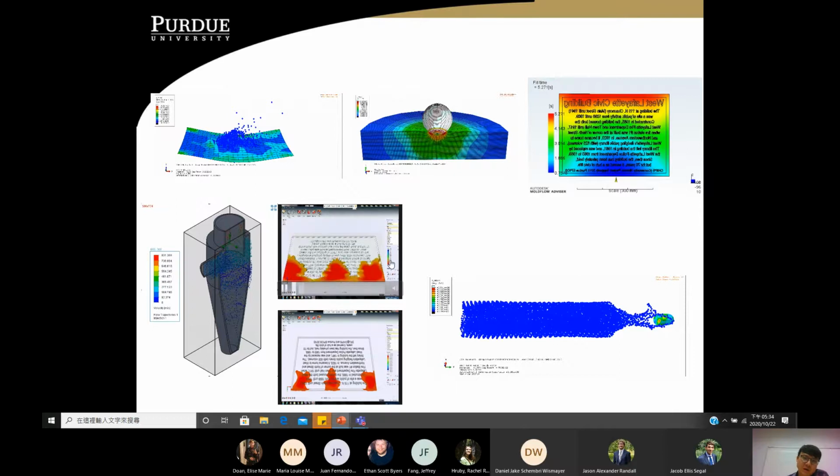You can see the aluminum filling the cavity and how it flows, so you can predict where it's going to solidify and avoid any cavities and voids that form. Over here, you can see how the voids form. If we pour at the beginning over here, the voids will probably form at the back.